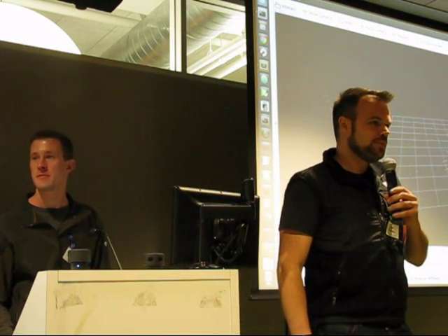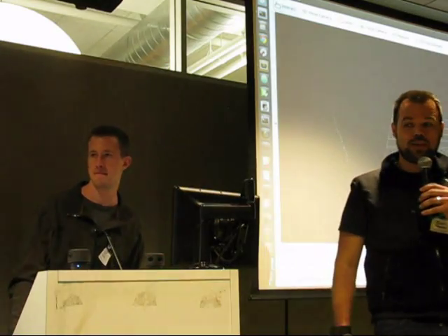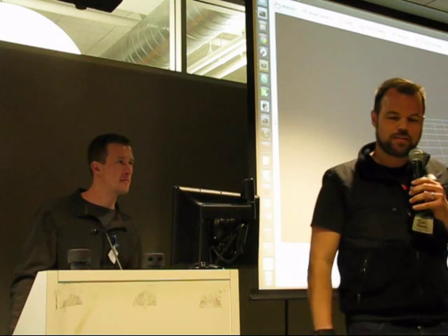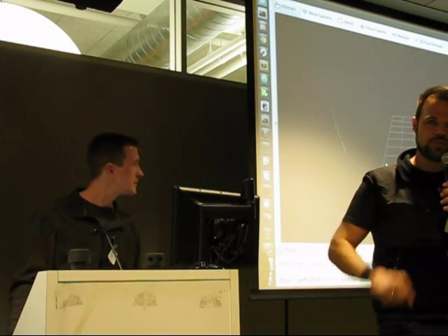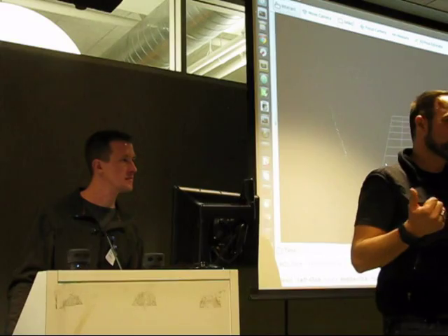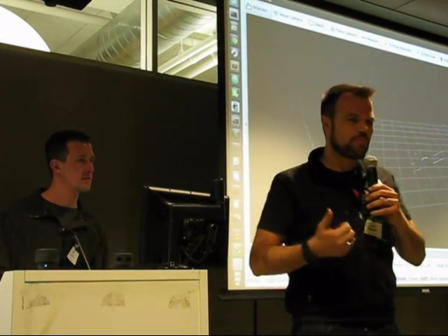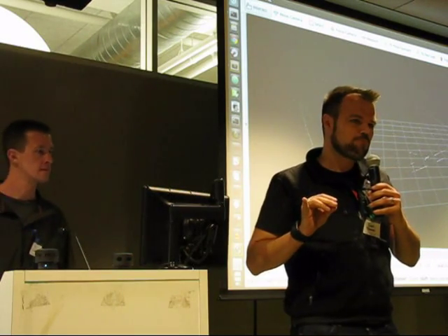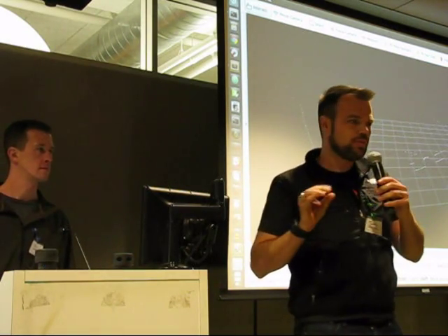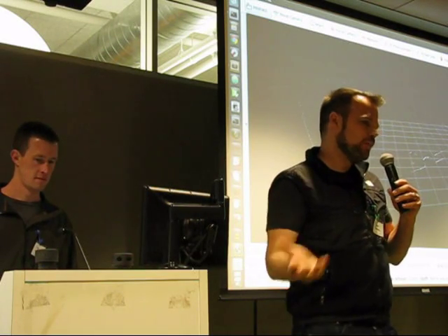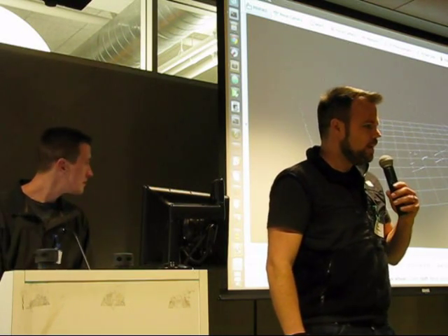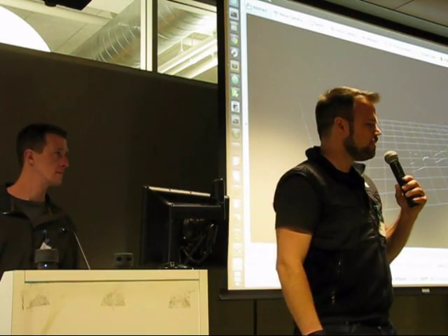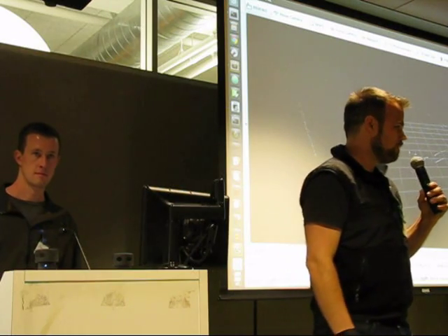Is it time of flight? Yeah, it's time of flight. So some of the big differences between this and what you've seen on the Neato there is that it's a true time of flight sensor. That's what gives us the outdoor range and light immunity. This is also using some newer technology that allows us to filter out noise much better than all the other traditional LiDAR out there. This allows us to use lower cost and lower power components, which is part of the reason why we're able to cut the price way down.